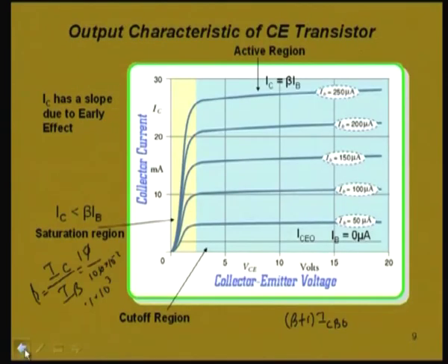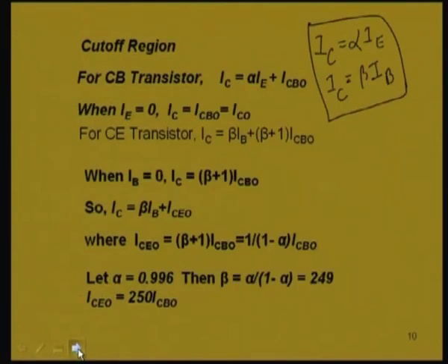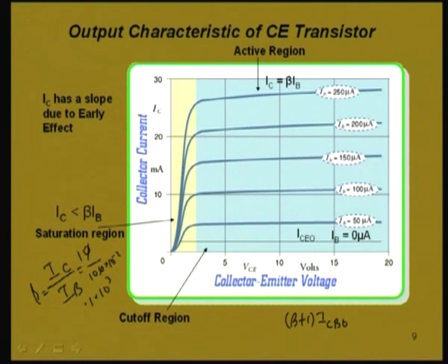Now, this study of input and output characteristics gives another relevant fact: the resistance in the input characteristic is very low, but in output characteristics the resistance of the transistor is quite high. That fact we can very well see in these characteristic curves. There is very little slope of the collector current.